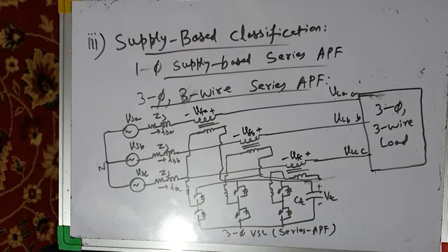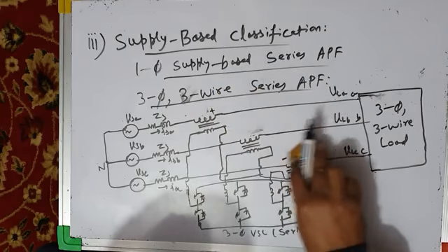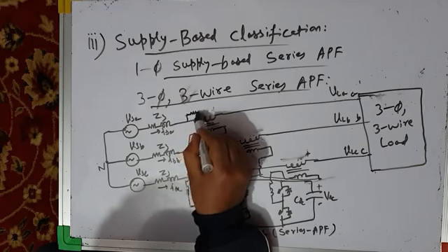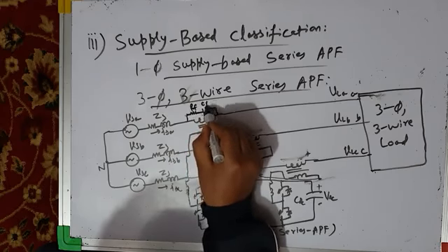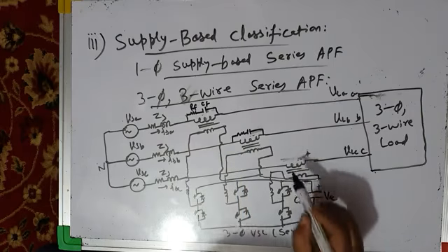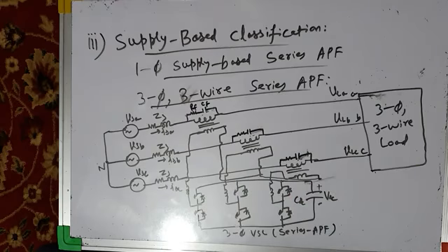Okay, and then you may have ripple capacitors also. I can show ripple capacitors across these injection transformer secondaries. Ripple filter, not ripple capacitor. This is RF CF ripple filter. Then this transformer secondary also has ripple filter. You have ripple filter across all the three transformer secondaries.